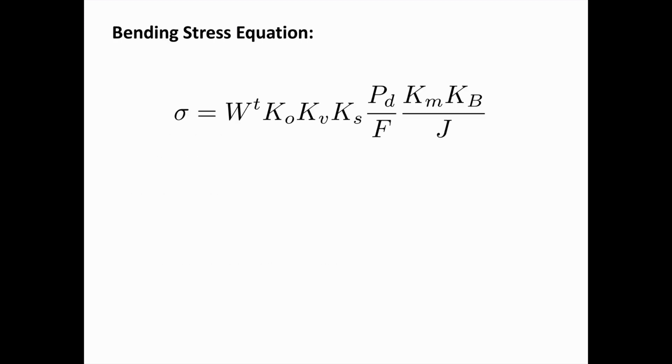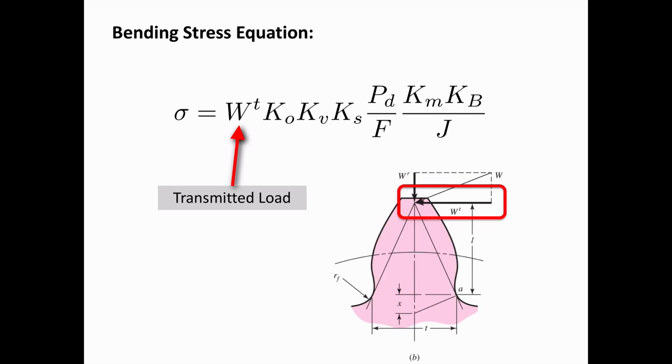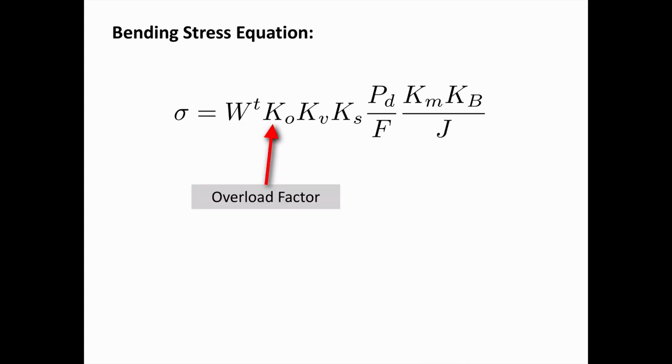So let's look first at the bending stress equation. We're going to step through each of these terms. This first factor is the transmitted load, which we defined just a moment ago. That's the force that is tangential to the gear tooth.